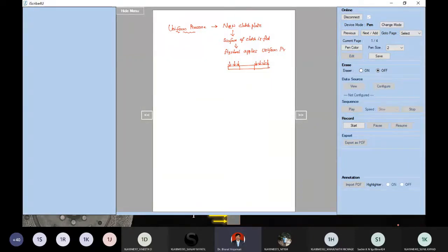Now there is one more condition, called uniform wear, meaning uniform wear rate. The entire wear is happening uniformly. This is not for new clutches; we use it for used clutches. What does used clutch mean in this case? It means the surface is uneven, or not uniform. Because it is getting used, this will be the surface.